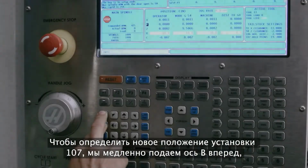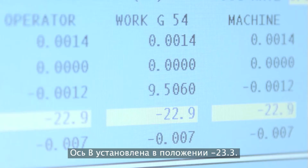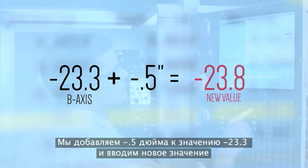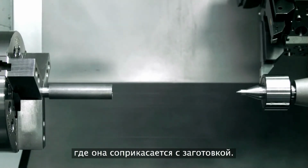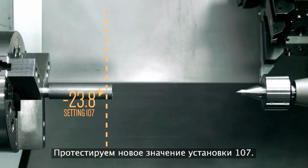To find a new setting 107 position, we jog B-axis forward until it touches the end of the part. The B-axis position is negative 23.3. We add negative 0.5 inches to the negative 23.3 value, and we enter this new value of negative 23.8 into the setting 107 hold point field. This way, the tailstock tries to clamp at a point beyond where it actually touches the part, allowing for minor variations in part length. Let's test our new 107 value.